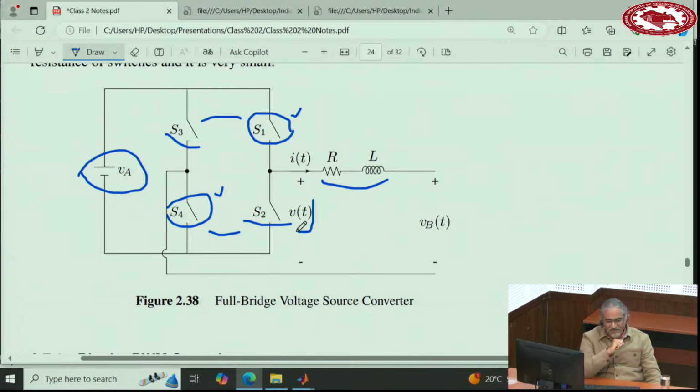Yeah. Right. Okay. So multiple advantages and basically no disadvantage. The only disadvantage is you need to have 2 more switches. Well, now we're comparing with the full bridge, so that's even 4 switches there. So no disadvantage. So the only question is how to operate it.